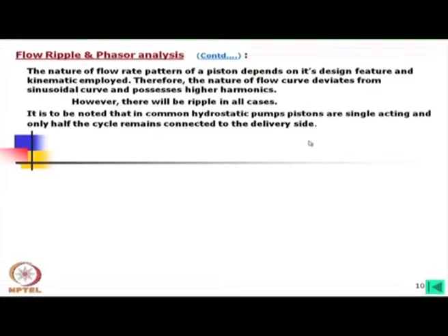It is to be noted that in common hydrostatic pumps, pistons are single acting and only half the cycle remains connected to the delivery side. You should know this double acting. Say for example, suppose you take a linear actuator which has a rod at both sides for equal volume displacement. Now, while it is going right side, then the left side is suction, it is accepting oil, whereas the right side is delivering the oil, and when it is moving to the left side, it is vice versa.